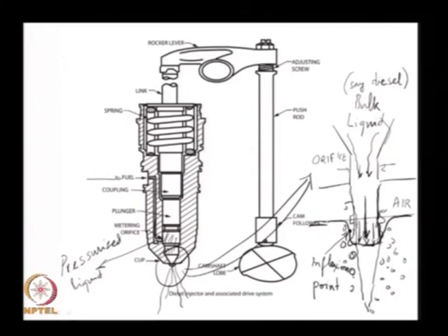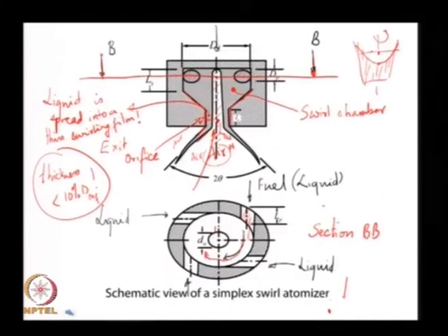So, or in fact going back the other way, in this injector design, the only way to get smaller drops is to increase the velocity of the bulk liquid, which if I do not change the orifice size means I am stuck with the same flow rate. So, one way to overcome it is to have multiple orifices injecting the fuel. So, for the same mass flow rate, while in this particular design you only have 1 degree of freedom, which is your orifice size, here you have 2 degrees of freedom, which is this tangential orifice diameter and their number as well as this orifice size.